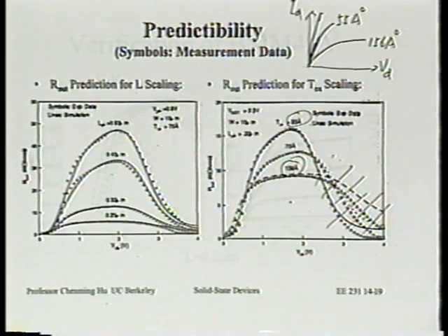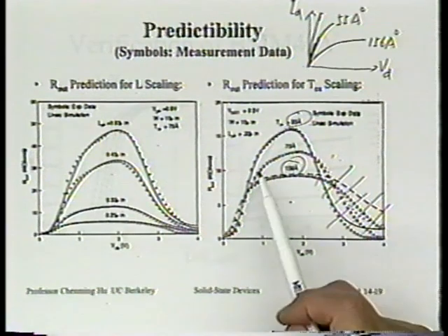Okay. Finally, I'm saving what's really related to channel length modulation for the last. Does this confirm or contradict what you expect the effect the thin oxide has on channel length modulation? Does this data confirm or contradict that? How do you tell which device has stronger channel length modulation based on this? A device that has very small channel length modulation would have very large R out, right?